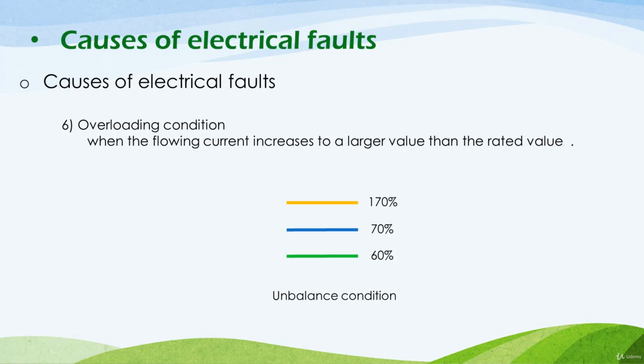The cable is designed with a cross-sectional area and a specific material to carry only 100%, but it is now overloaded with a very large value, which is larger than 1.5 times its rated power. So in that case there will be a failure in that phase, as its insulation will be broken, and it may also be damaged or burned out due to the excessive power that this phase cannot withstand.